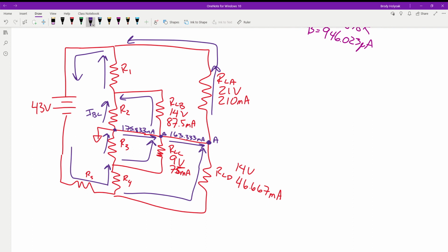Just working our way back, we're going to have current that's coming up here. Any current that's in this spot has never touched the load. If this was coming in and then it has to turn this way, we would get current from these guys coming back this direction. So this one has to be it because it's the only place that we're going to have current that does not ever go through the load.